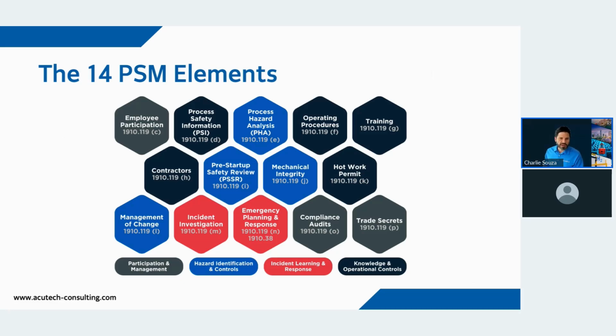But you can see, I will say ahead of time, that functional safety engineers will recognize some of these as also present in the functional safety management or the functional safety life cycle. In other words, they're required on 61511. And as you can see, they are required by OSHA PSM as well.